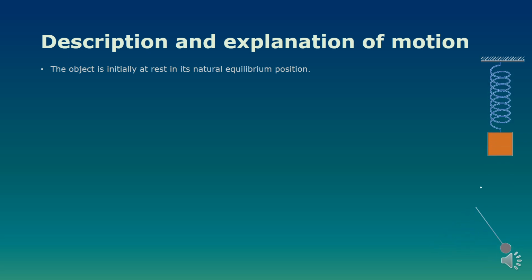Now, when dealing with these systems, you can consider all the forces acting on them. It does make the maths much more tricky. Because these forces are already acting in a stationary position, what we really look to do is just look at how changes in forces, so changes in the tension, for example, because obviously the weights won't change, how the changes affect the motion and create a resultant force. So it's easy, for example, in the spring mass system just to ignore the weight because that's constant all the way through. So there's always a component of tension that's countering the weight, but it's the change in tension from that that contributes to the motion.